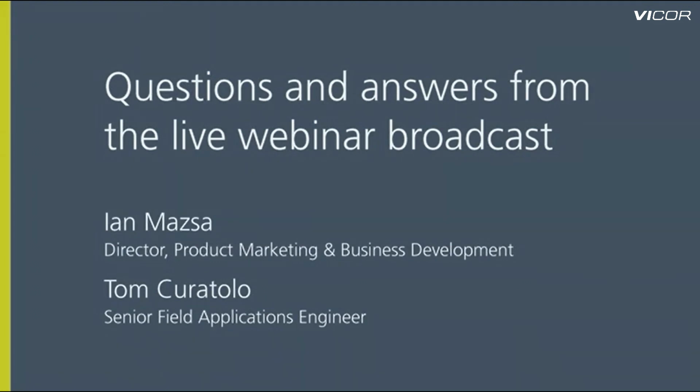What is the size and weight of Vicor's fixed ratio converter? I'll take that. That's an interesting question. Vicor refers to the fixed ratio converters as BCMs. And in the part number, we put the dimensions. As an example, a BCM 6123 refers to a 61 millimeter length and a 23 millimeter width. That part is under 7 millimeters in thickness, and the weight is roughly 61 grams.